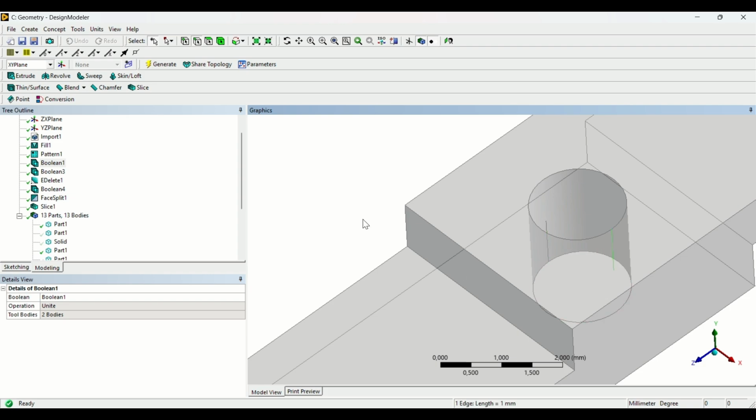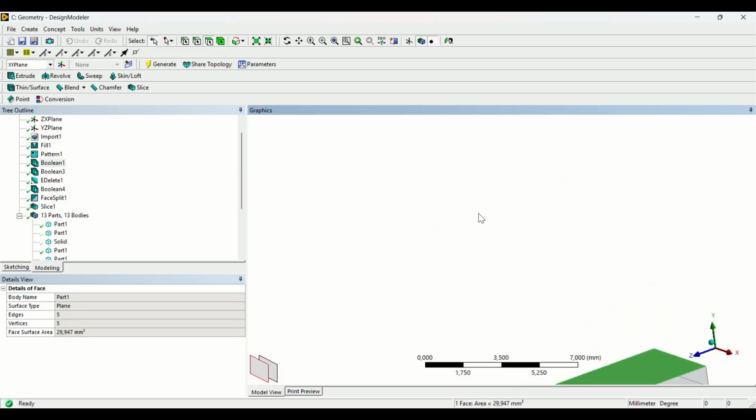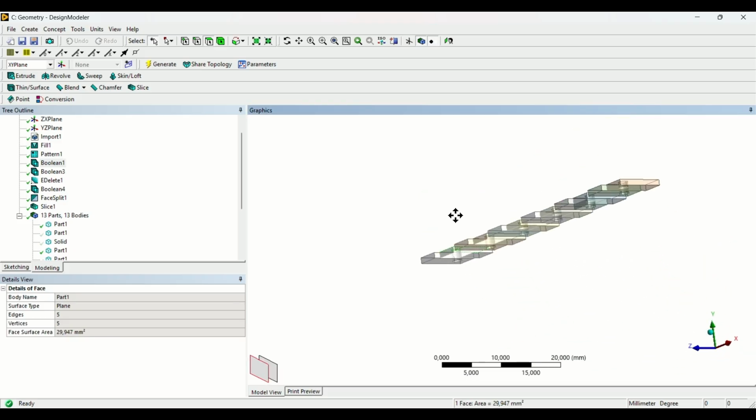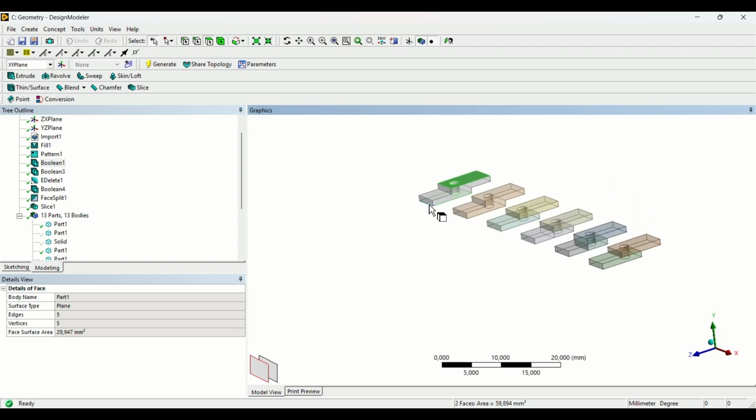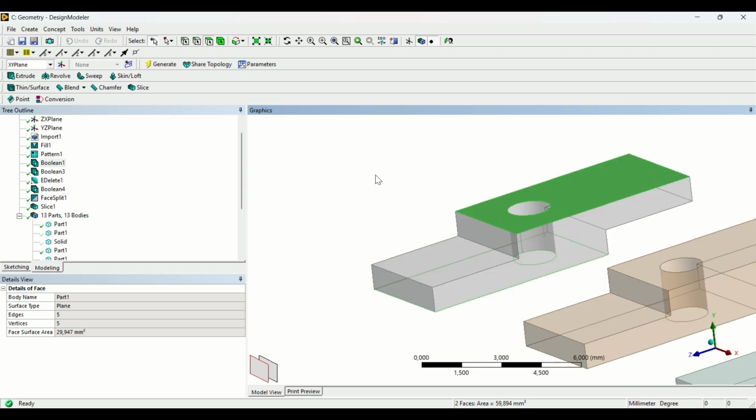So right now it is very important, when I'm going to create the mesh, that I don't have these lines, because they can cause some problems when creating my mesh, and it will also depend on what type of mesh I'm going to create, because sometimes these lines are necessary. In this case they will need to be from one face to the other. When I'm talking about faces, I'm talking about this one and probably this one. So the line should be along all these two faces.